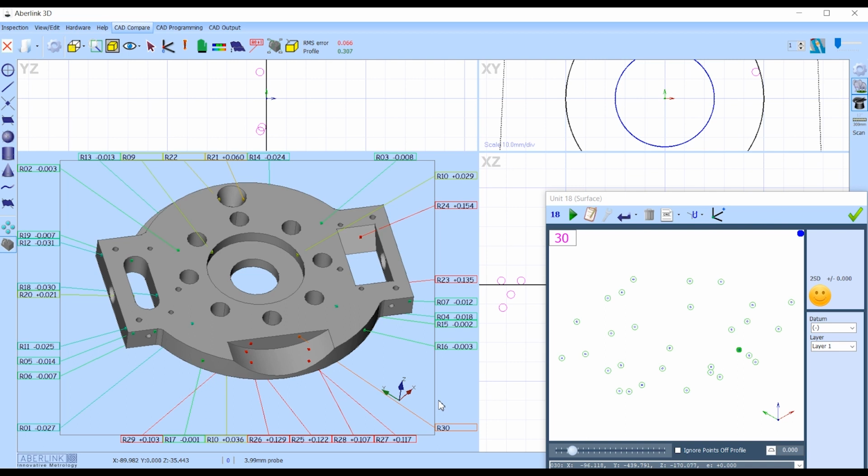So as you can see, I've done 30 points at this stage. Majority of it is in green, which is all the 2D planar, more critical features. And of course the cone, planes and the cylinder are all oversized condition for clearance. This part, I'll just do a couple in the PCD holes to see how close they are, because we want to make sure and ensure that they are in the correct position. As you can see, they are popping up very, very accurately.